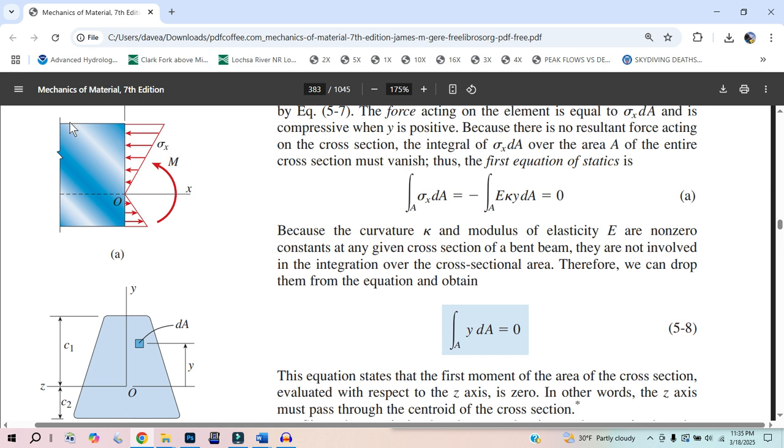So if you turn this into a free body diagram, I would put a force area. You have to use calculus, but we're just going to take this little area. And then I would put an arrow that would be 10,000 pounds right there. Cool. And then I'm going to go to the top and do the same thing. Let's say this area is just half a square inch, but the pressure up here is twice. It's 20,000 psi. So I'm going to have another arrow up here that's 10,000 pounds.